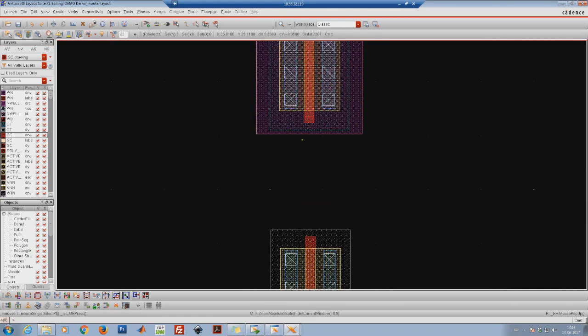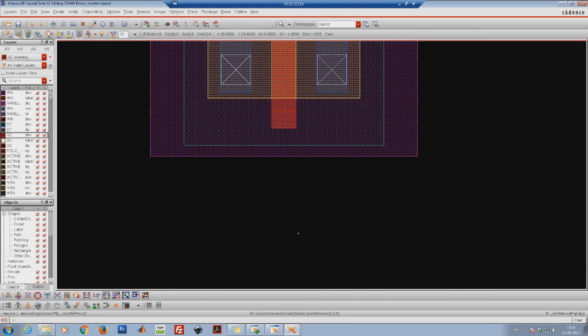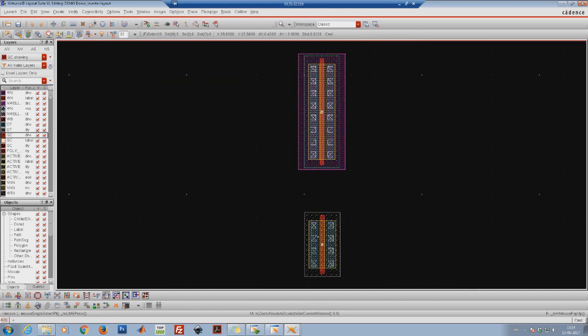So now I am sure that GC is the polysilicon layer, and using the polysilicon layer I can connect these two gates. The polysilicon layer is resistive compared to the metal layers. However, for short distance connections, like connecting the gates of the inverter or gates of some small circuit, it can be used, but preferably long connections should not be done using the polysilicon.